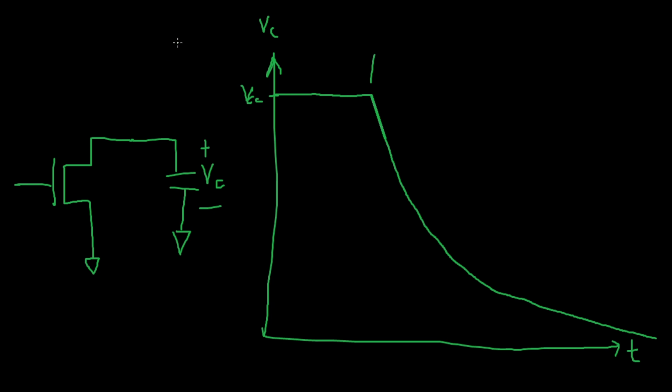For example, if we were to have a device that was operating at, say, 1.8 volts for the voltage here, and it was open drain and we had 5 volts on the output, then we would see, assuming this was 5 volts, and 1.8 volts is way down here, then when it switches we're going to have a linear response all the way down until one threshold below 1.8 volts, instead of way up here close to 5 volts, which was my other assumed VCC.